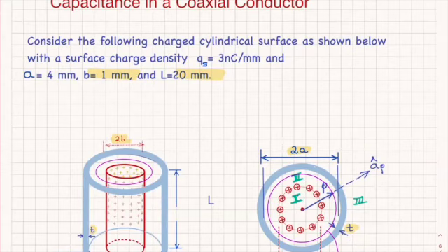So this is the coaxial, and the parallel plate are the most useful, as I will show you towards the end of electrostatics, which is going to be sometime next week. I will show you how you go from parallel plate to microstrip, what people are using primarily in printed circuit design, and coaxial, which is for higher frequencies. There are different variations. People are using it for high frequency applications, usually ground stations, when you have the repeaters on ground stations, usually they will use coaxial cables.